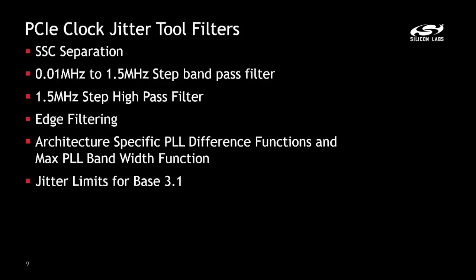The reason for this is because some of the jitter will be tracked by the transmit and receive PLLs and some will be removed, so the final result at the CDR latch is the only jitter that will impact the performance of recovering data. In revision 3.1 of the PCI Express base specification, 5 filtering operations are applied to the data: spread spectrum clock separation, a 0.01 to 1.5 MHz step bandpass filter, a 1.5 MHz step high-pass filter, edge filtering, and architecture-specific PLL difference functions.